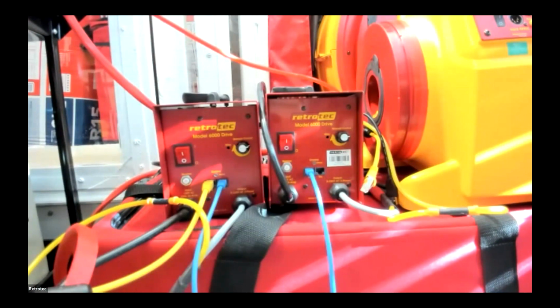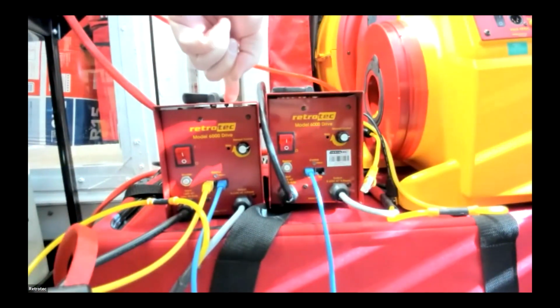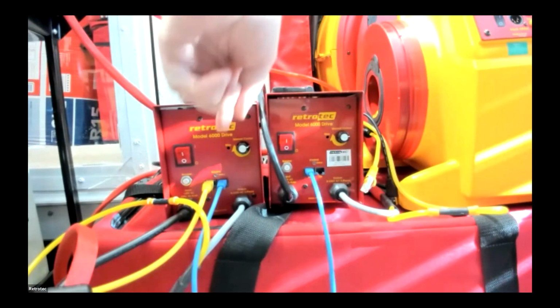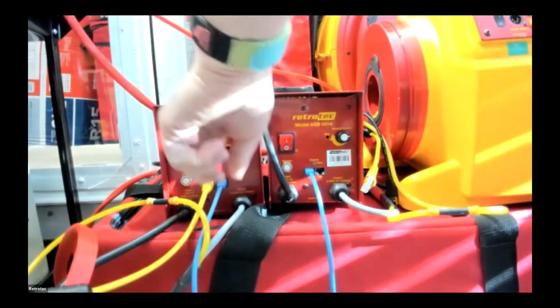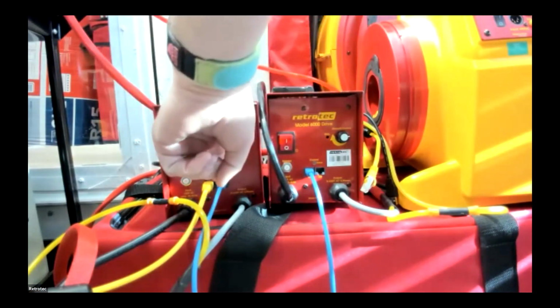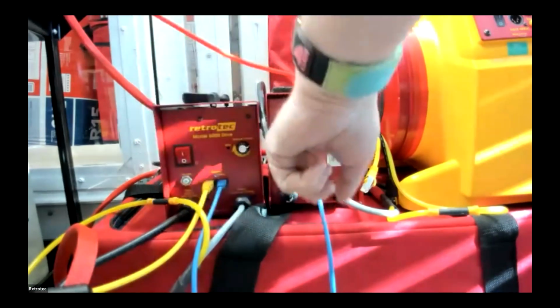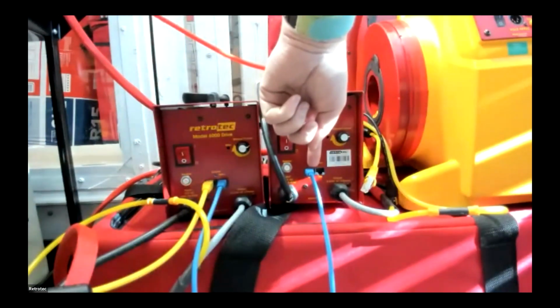It's going to require what we call common control, or daisy chaining the gauges together, or the fans together. You'll have a primary fan. In this case, this is our first one on the line, and it's getting a signal in from a manometer in this in port. Then all we're doing is taking another data cable, a Cat5 cable, and connecting from this gauge's out port going into the next drive.